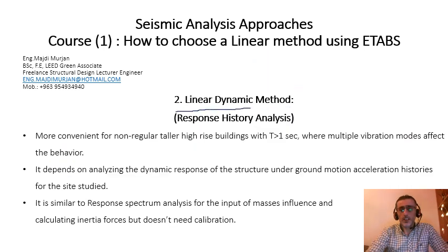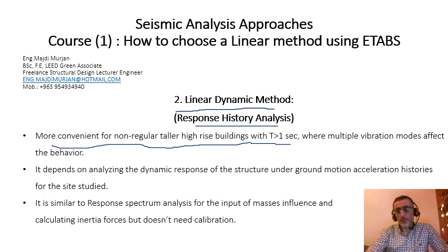Another linear dynamic method is the response history analysis, which is more convenient for non-regular, taller high-rise buildings with T more than 1 second, and this response will not be controlled by the first mode of vibration, but multiple vibration modes affect the behavior.